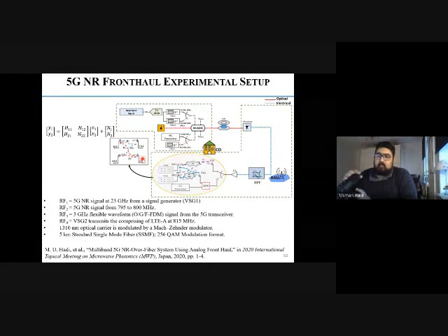So we would like to move RF2 from 795 to 800 so that we can see how much interference there is when you bring 800 to within 15 megahertz of 815. If you take it to 795, you move from 795 to 815, which is around 20 megahertz. So we would like to see how the interference appears in the electrical spectra. We will see in the next slides.